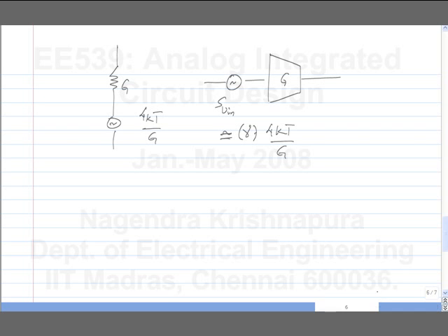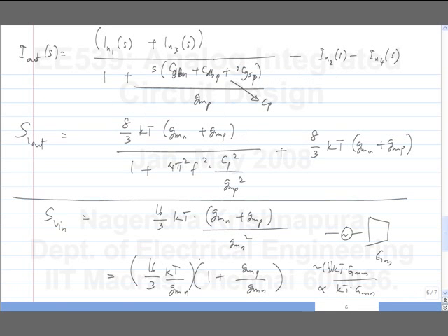Next, this is dependent on implementation. So, typically you will get this much also because you will have something on top of the NMOS transconductors. Okay, we will see this again in our examples as well. We will have 1 plus GMP by GMN. And if you want to absolutely minimize the noise, you have to minimize the value of GMP. Is it okay?